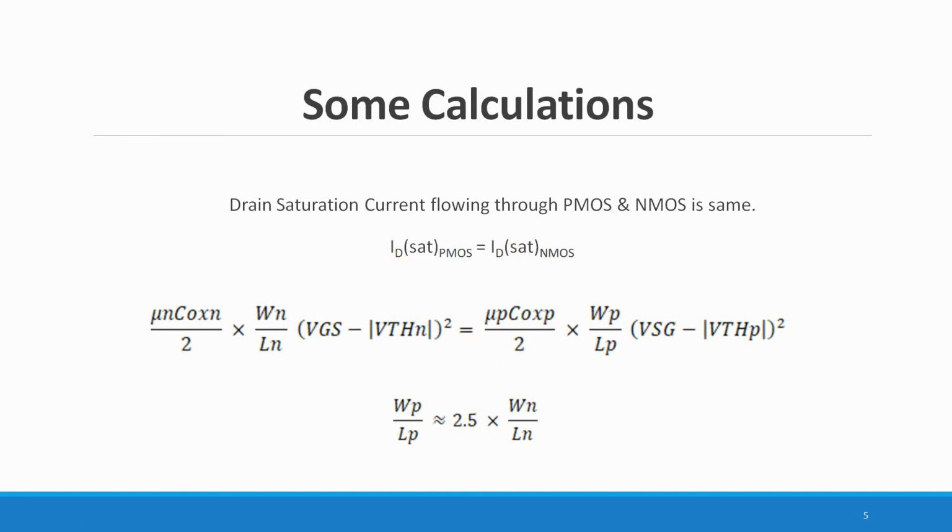But what happens at the fab, at the nanometer level, where thousands of inverter circuits are fabricated within a single wafer, is that meeting this condition becomes too crucial, and hence the current flowing through the PMOS and NMOS fluctuates. These are transistors, may be PMOS or NMOS, so they will have some output resistance, and this fluctuating current can cause a voltage drop across the PMOS and NMOS, and due to this fluctuating current, the output also fluctuates.